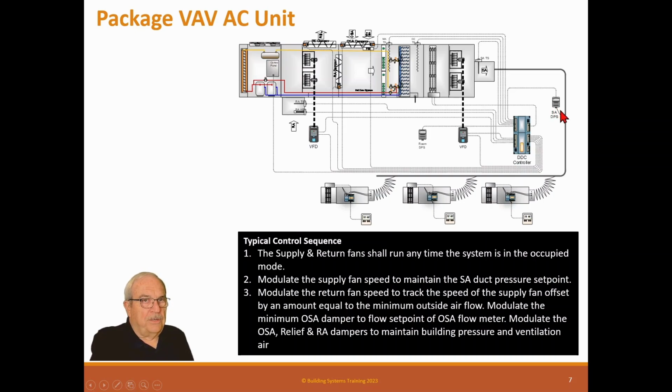This is the pressure. So if we keep that pressure, we know this will always work. And as these start to close, this pressure wants to climb, but this sensor says, nope, slow it down. We don't need any more pressure. So it'll start slowing these fans down to maintain that pressure.